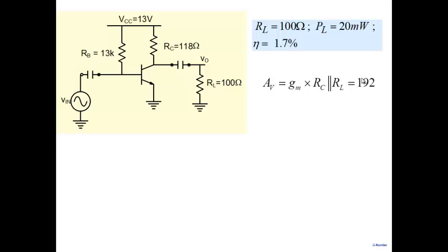And what can you do? Sacrifice the gain and get what? If you sacrifice the gain, what do you get? You get all the benefits, and one of the benefits that you get by using negative feedback, if you sacrifice the gain, is distortion goes down, linearity increases.